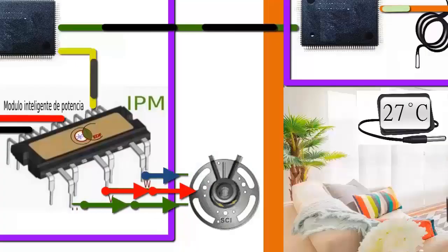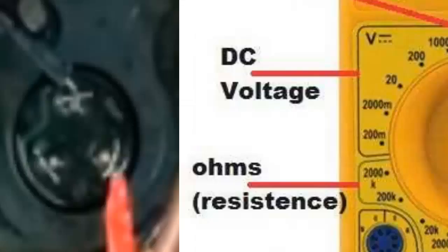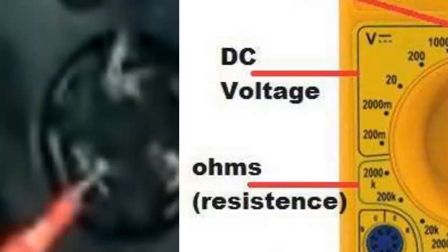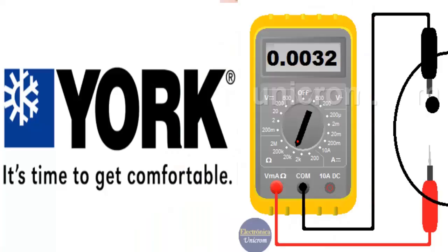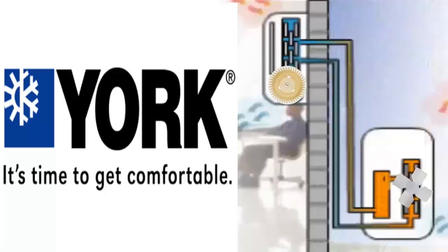You can disconnect the unit from electricity and use a multimeter set to the electrical resistance scale to measure the value of all the internal resistances of the compressor motor coils. To do this, measure the values between two power connection pins of the compressor. All readings should be equal. Check the electrical connections between the external and internal units, looking for loose points that could cause poor electrical contact.